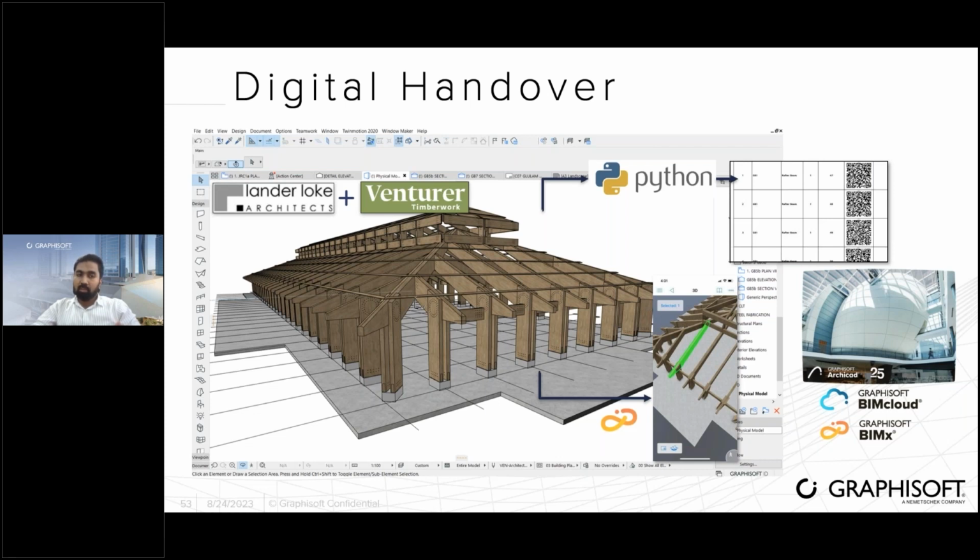Exactly the same thing can be done in the facility management stage. You can print the QR codes for all your equipments that you want to perform maintenance on, and then paste them on those. When you scan it, it will open the BIMx model and zoom into that particular element and highlight the element for you, so that you will be able to check the 3D data or even the metadata that is attached to that particular element. And if you have the facility management system integrated with BIMx, which we are going to see later, you can access that information as well, the facility management system information inside the BIMx, by scanning the QR code like this.